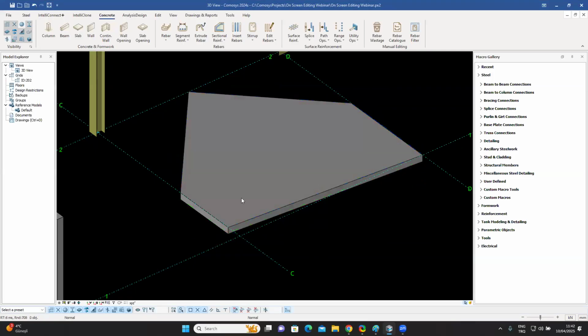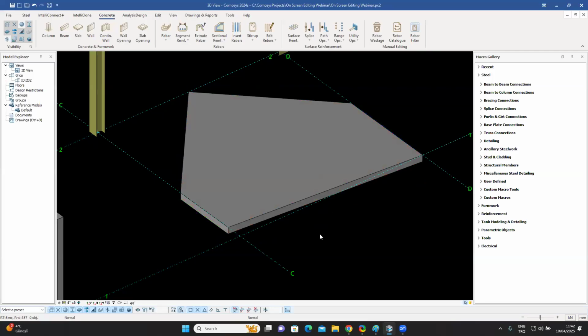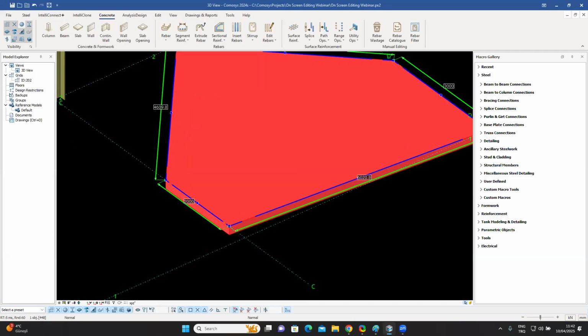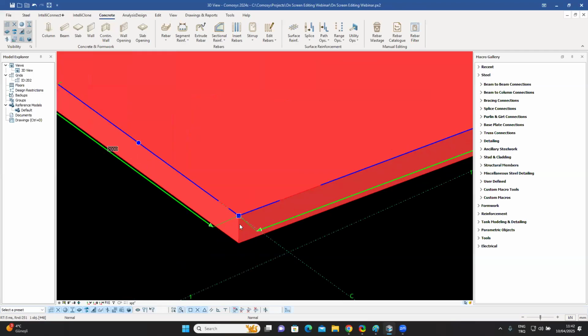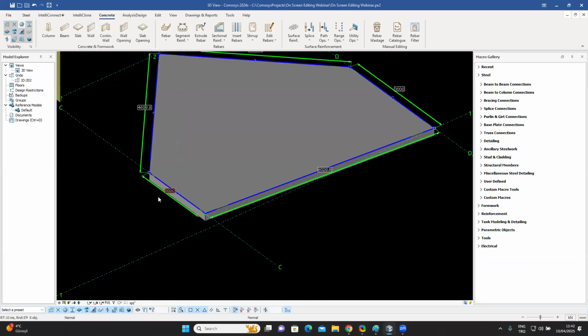So if I select it, I can press Control W, and you can see that the plate is being offsetted like that. If I select the plate, once again, you have the same handles, the arrow, the endpoints. If I select the arrow, I get the same. I can move it a number, or I can make it extend to a surface, just like we did last time. I can introduce midpoints as well.